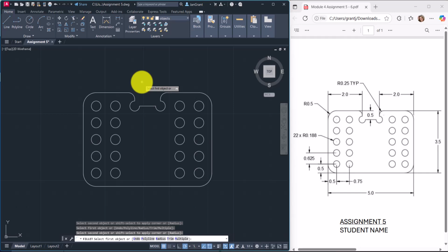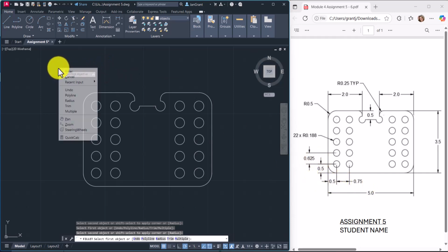So we have another new thing that we're going to be looking at. We're going to be looking at using the leader in this one and not always linear. So we'll have that as kind of an experience, and changing the precision. Not sure, I don't think we did this yet, where down here at the bottom left we have numbers that go 2 places to the decimal, one that's 1 and one that's 3 places, so we can change that as well. All right, right click and enter.